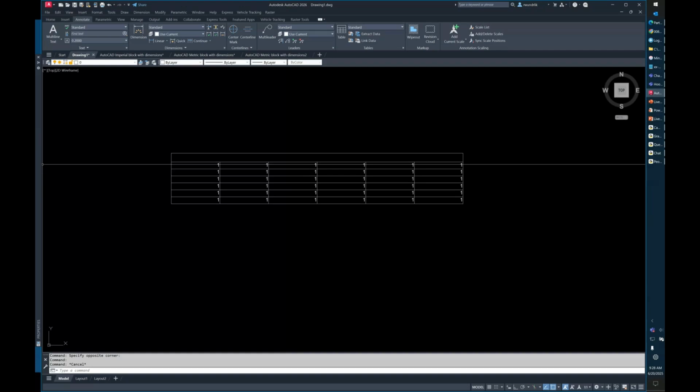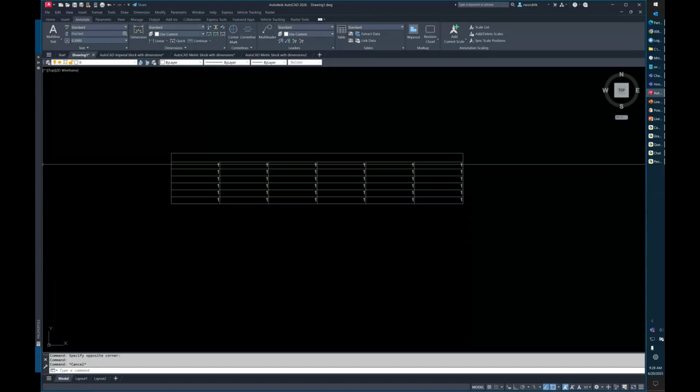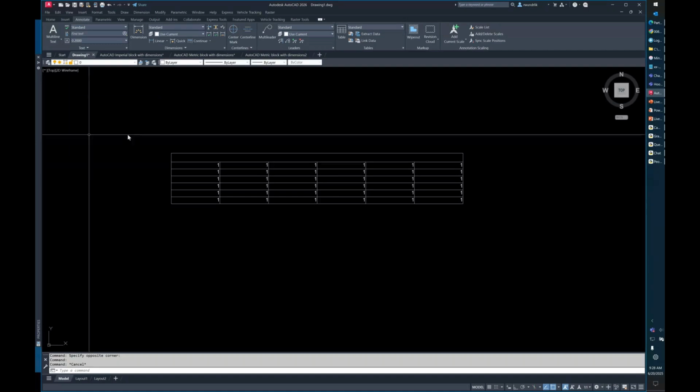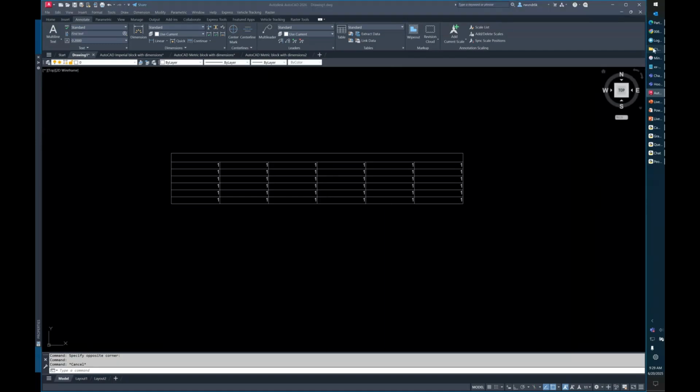And if you have special characters, my question is if you take that drawing file and you move it closer to the root, or you move it to, like C:\Autodesk, will the file open then? If it does, then there's something wrong with the path you're trying to get to. If it keeps coming back and telling you drawing file is not valid, that usually means that there's a corruption. So what he's talking about is here. Let's go to here.